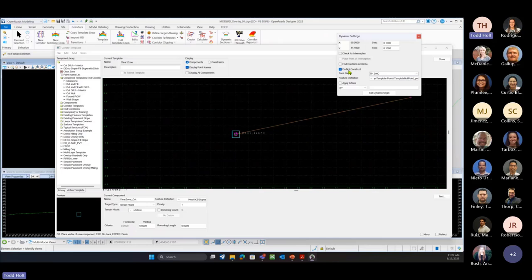So this is going to draw my end condition, but I won't see this end condition as a component when I would draw. So I'm going to use this as a search criteria to see 18 feet out from our hinge point or that slope, but I'm not going to construct this element. All right, so that's the only difference on this TP, this do not construct, is I'm using this to control it to be 18 feet away, building in that criteria, and then I'm going to build a fill slope and my cut slope.